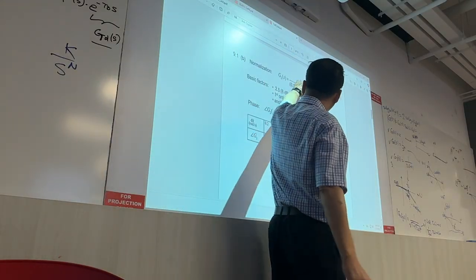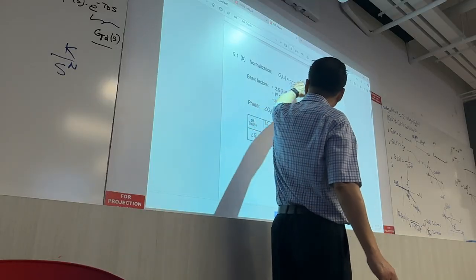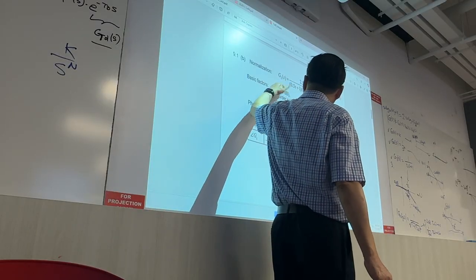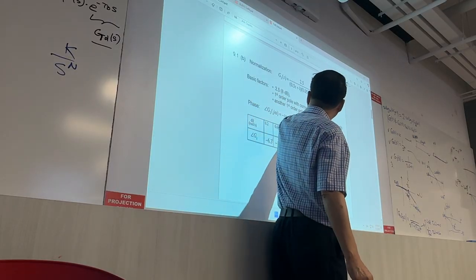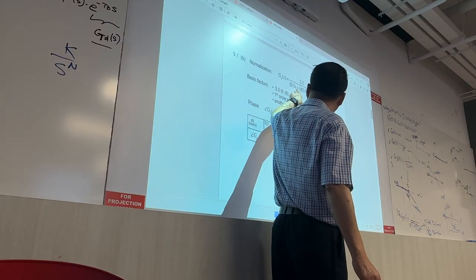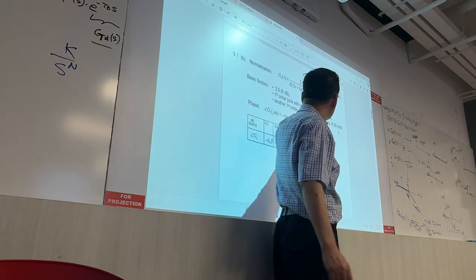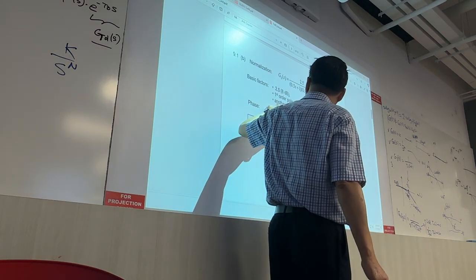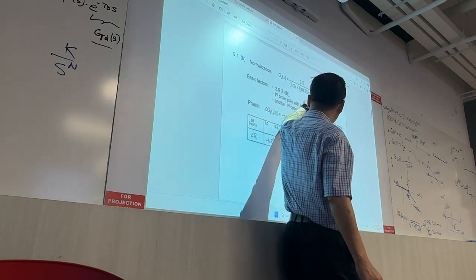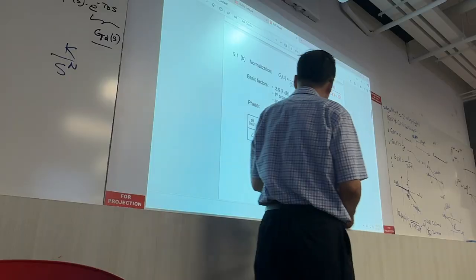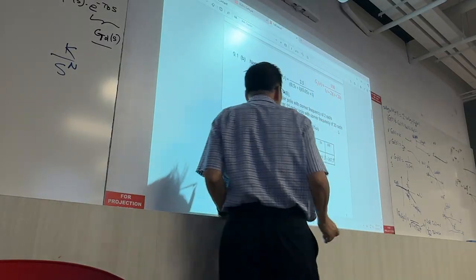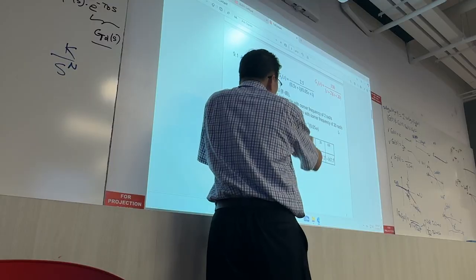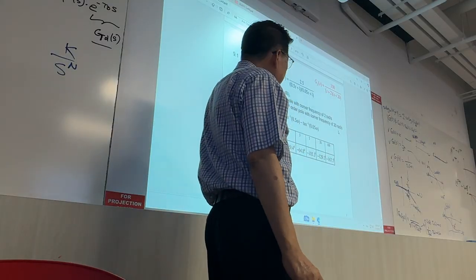So in this case, we identify 3 basic factors: 2.5, that is 8 decibels. And then the first order one with the corner frequency at 0.5, 1 over this, right? That is a pole. Another one is at this, which is 20 radians per second. And then for the phase, we can write down the formula and then generate the table.